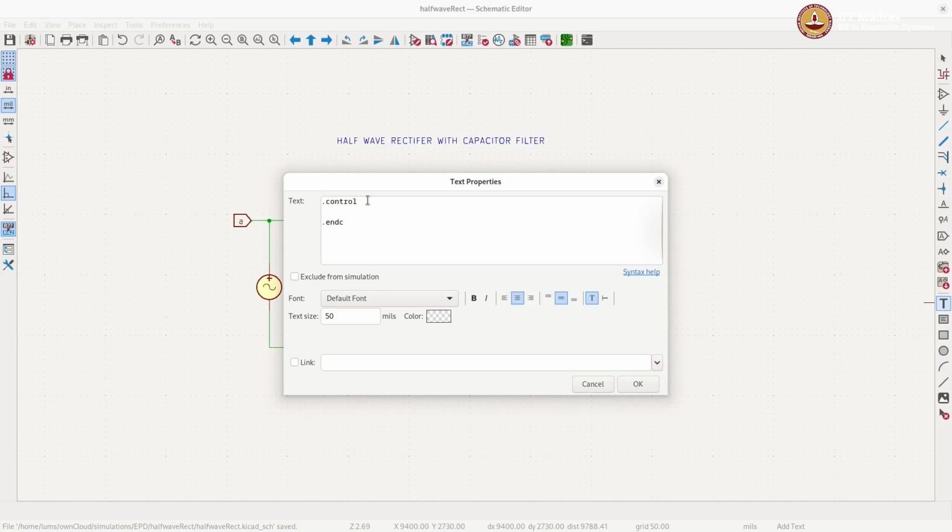What are the control statements? I would like it to do a transient analysis. So let me type in tran. Tran is the command for transient analysis. In steps not exceeding 1 microsecond, up to 100 milliseconds, 5 cycles. 50 Hertz is 20 milliseconds, and therefore for 5 cycles, I have just put in 100 milliseconds. And I will say UIC, use initial conditions if they are there. So I just put this one. Then I will ask ngSpice to run this command. And then let's see what happens.